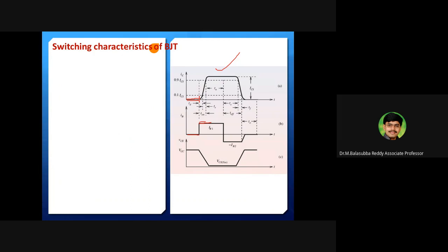Device is going to be turned on. So it is from zero onwards, it gradually turns on. Once the device is completely on, what will happen? The collector current will be present, because how long will it be on? Until then it maintains the collector current. Whenever you want to turn it off, the collector current gradually decreases and finally reaches zero. If the collector current is zero, that means the device is automatically turned off.